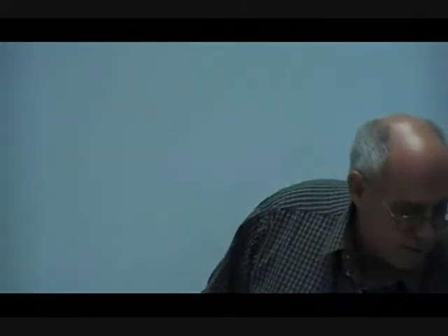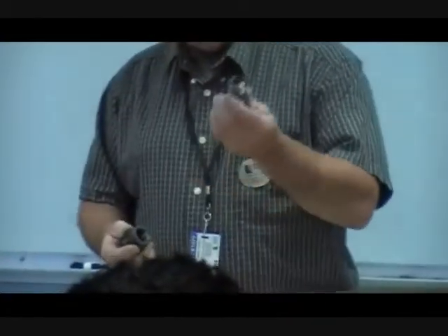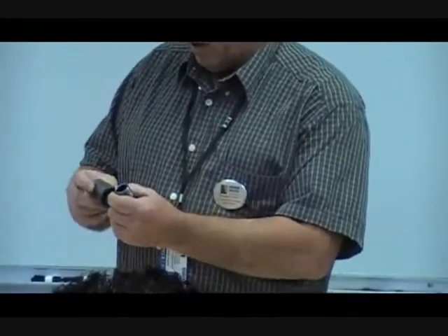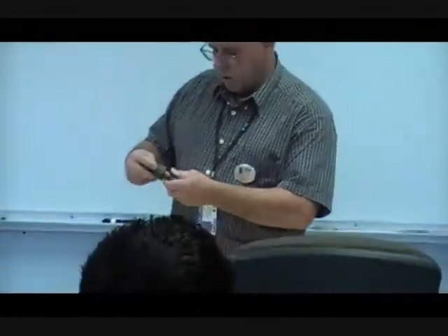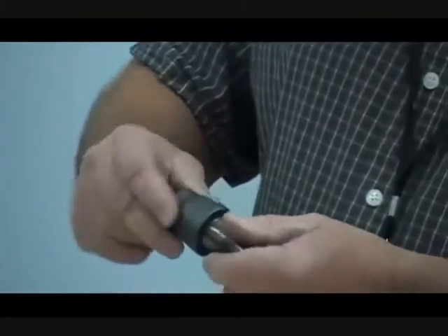Fuel lines in particular, though, we're going to be looking at iron pipe. Now there are other pipes that can be used for fuel lines, but one in particular is black iron. Now, I want to show you a little something. The threads on a black iron pipe, I have a short nipple and a reducer coupling here, and I want to pass this around. And I want you to look at how the threads are, hold them up, and take a close look there. I'm going to draw something on the board that's going to help us out too.